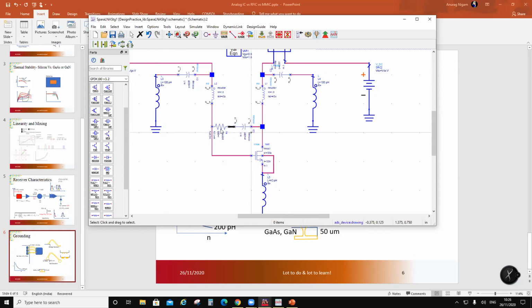Now this is also a high frequency feedback. What it is doing is called lead compensation. It'll take a right half plane zero and put it on the left half plane. So there are two poles there: one is going to be the dominant pole, the other is going to be the second pole. When you introduce a zero in between, it will give you a phase of plus 90 degrees, while the gain would roll at minus 20 dB per decade. So it will improve your phase margin. This is what you call lead compensation. So this is a lead compensation here.